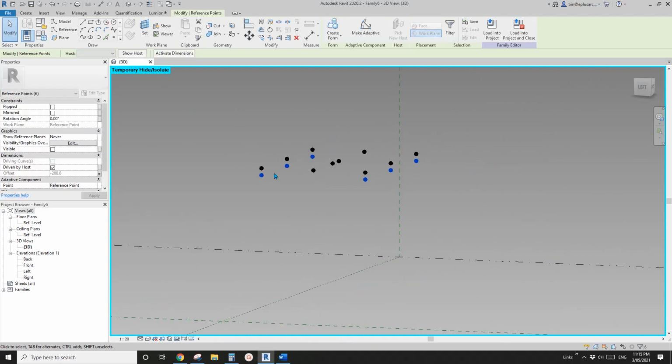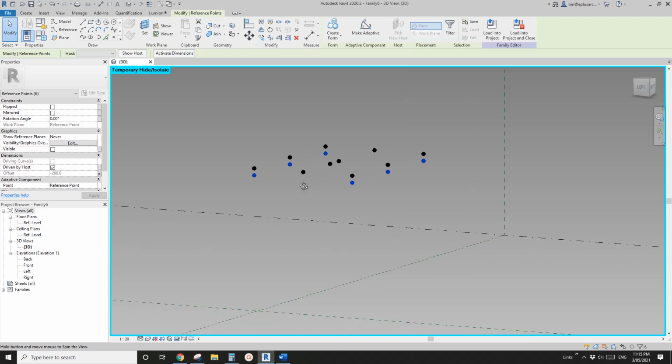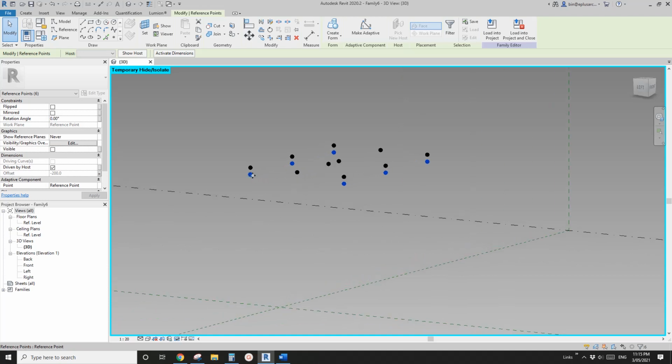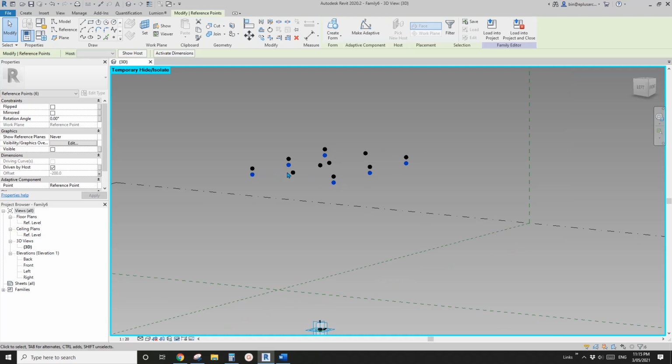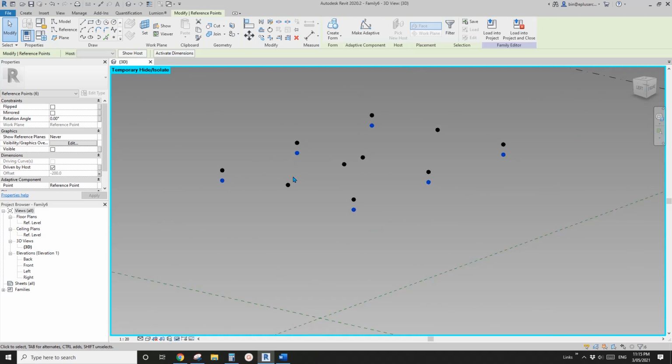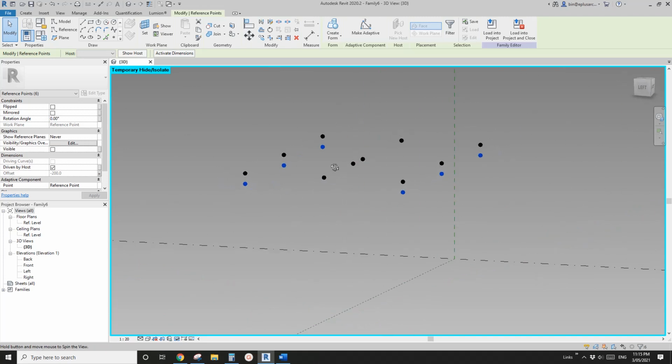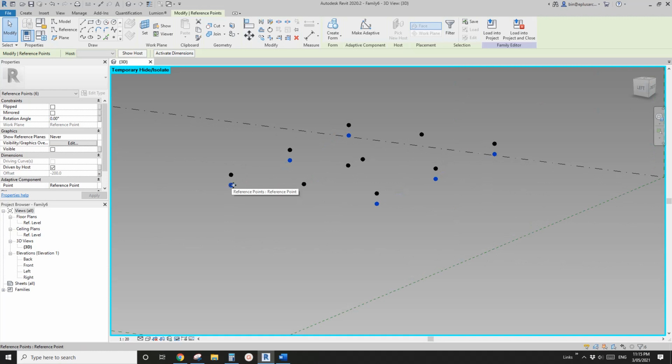And then we have this, but we still don't have a thickness. So what I'm going to do is, because I want to control the thickness and the drop differently, so I'm going to offset another 9 points from this point up to create the thickness.